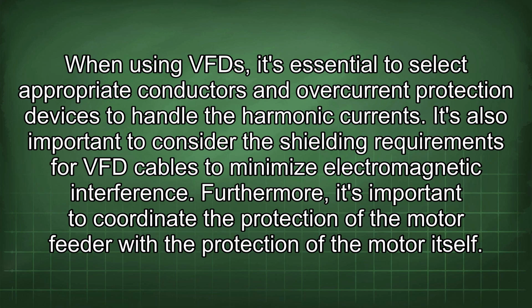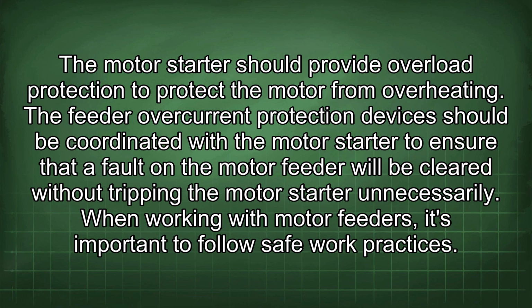Furthermore, it's important to coordinate the protection of the motor feeder with the protection of the motor itself. The motor starter should provide overload protection to protect the motor from overheating. The feeder overcurrent protection devices should be coordinated with the motor starter to ensure that a fault on the motor feeder will be cleared without tripping the motor starter unnecessarily.